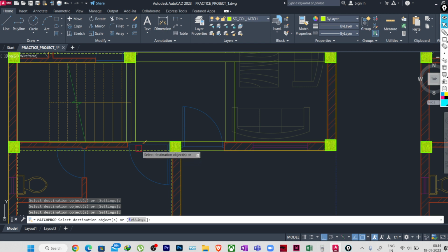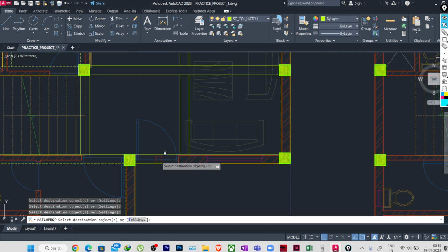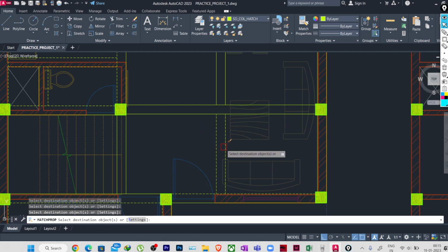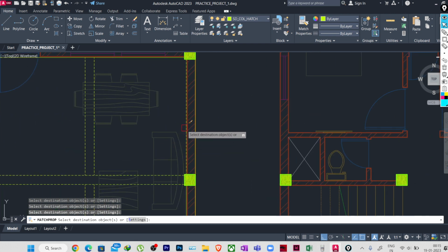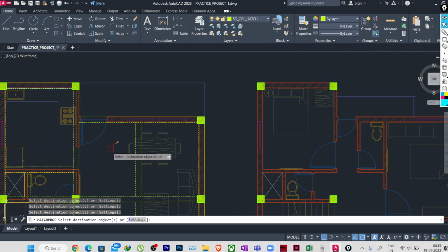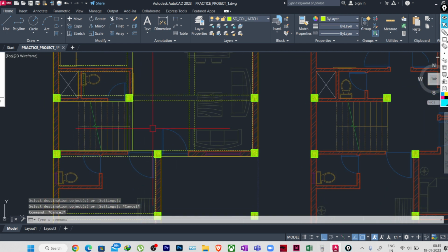Now here this beam, after the stairwell, this edge will be visible, no problem. Here we will have the slab actually, so from here it will be dotted. I'll change it later. Let me select this, it will be dotted, this will be dotted, this line dotted or dashed. Whatever line will be flushed with the slab, I'm showing it as dashed.